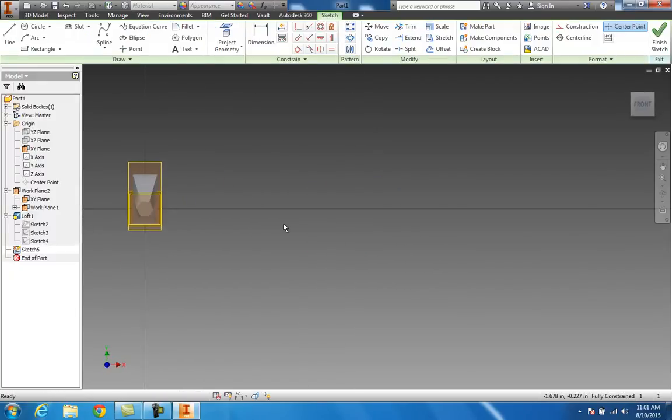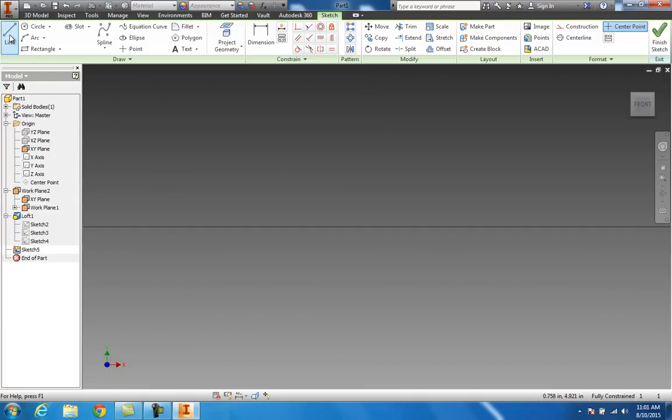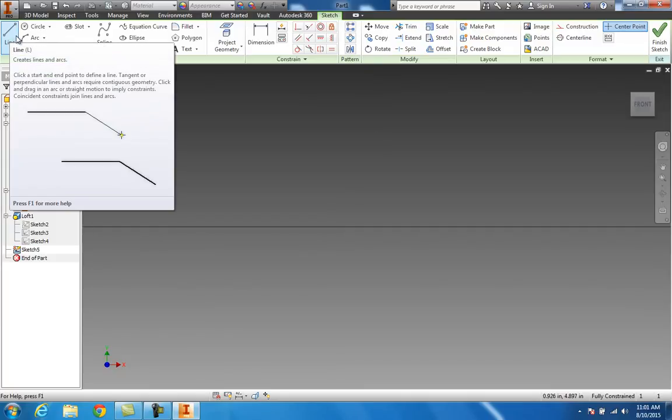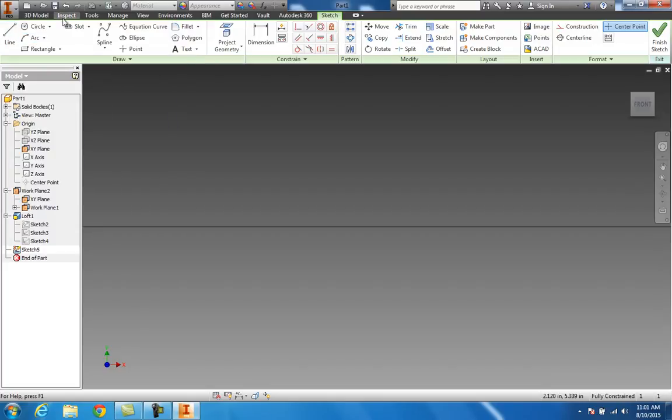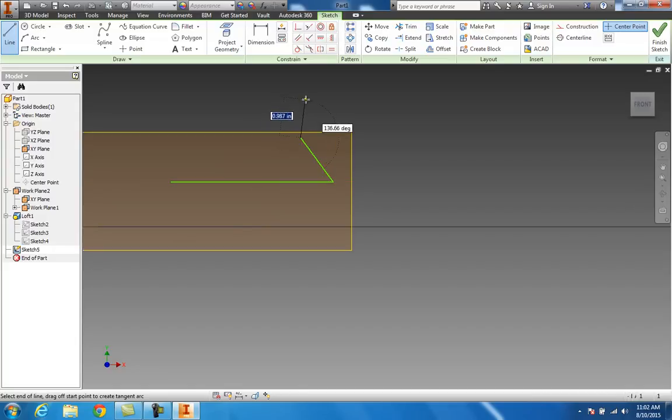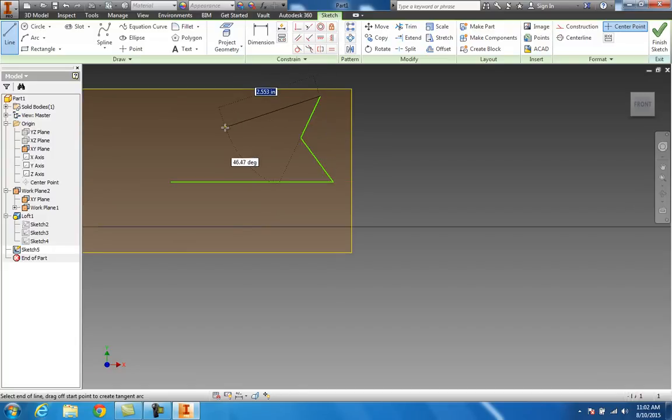And we're just going to move that to the side. Now, Revolve is you're drawing something that's symmetrical. And what I mean is symmetrical is both sides are the same. So you only have to draw one side and then revolve it. It's a really cool tool to use. Say this part starts out like this, got a hole through it maybe. I'm just drawing something in here like that.